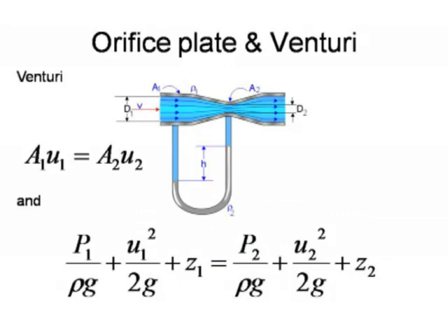If we just look at the venturi to develop the equation, it's the same equation for the orifice plate. Taking the venturi, we have the flow constricted down to its narrowest point, and that's marked as having an area A2. The flow approaching the constriction in the full bore of the pipe is shown as having an area A1. That's internal areas A1 and A2. And the pressure difference between those two positions in the pipe is measured as that height marked on the manometer there.